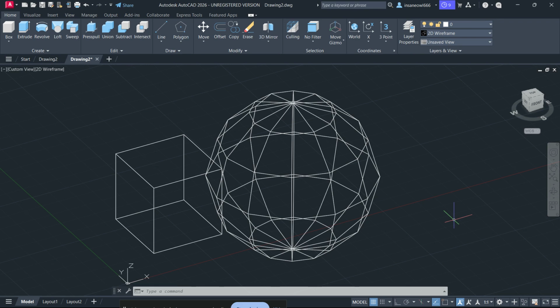So to quickly recap, error code 18050 usually means AutoCAD cannot complete a Boolean operation because the geometry is ambiguous, invalid, or too complex. Start by forcing a small overlap, then clean the body, check the solid, simplify detailed features, and if needed, re-solidify or scale the model up before trying again. One of these steps will usually get your 3D operation working properly again.